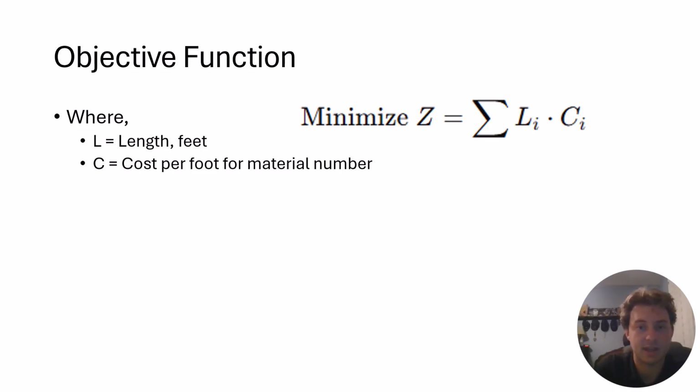The model uses the Hazen-Williams equation to evaluate each pipeline's head loss and velocity, ensuring that all parameters stay within acceptable limits. To reiterate, the cost for each individual pipe segment is tied to the material and size selected by Excel Solver. The best solution is the lowest cost combination that still satisfies all hydraulic constraints. This helps us avoid overdesign, reduces unnecessary expense, and results in a system that is both efficient and affordable.